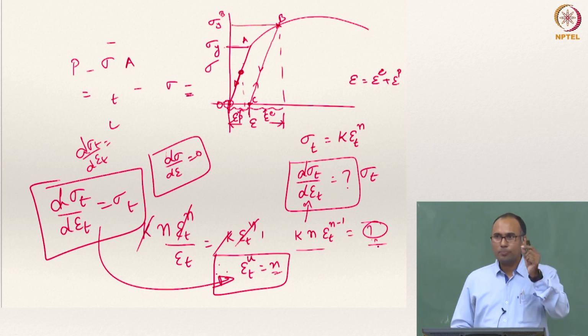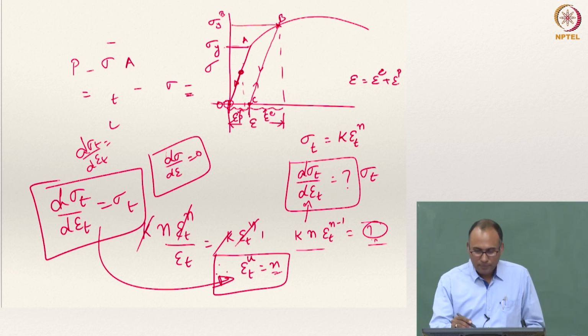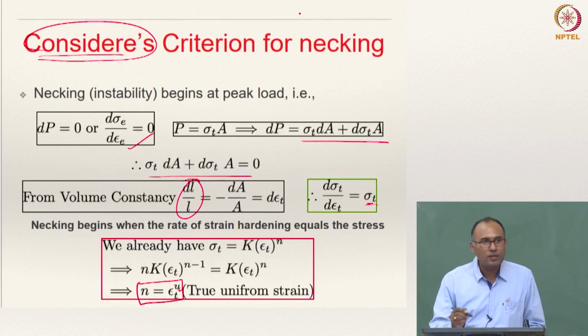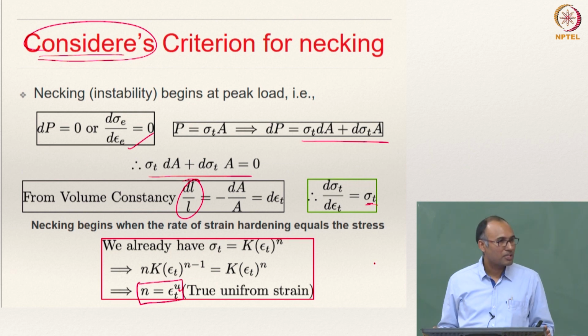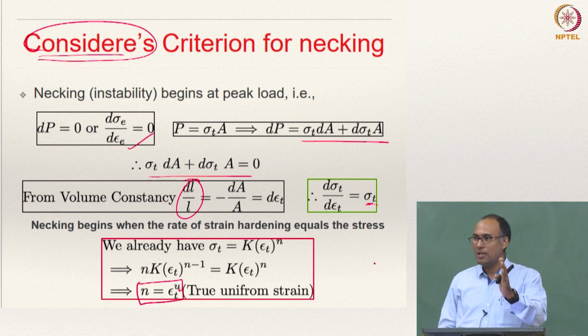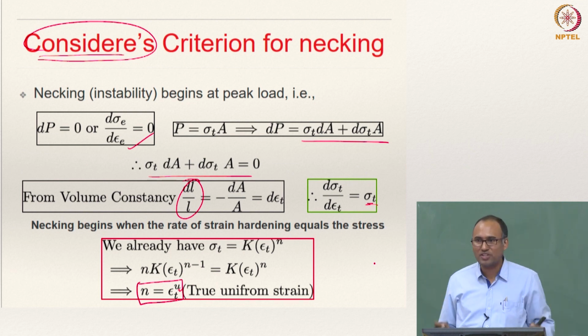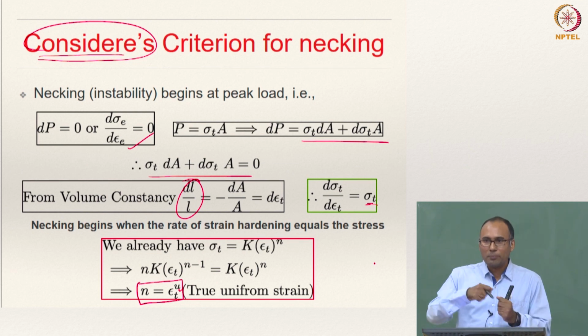So the most important point to realize is that when we are moving along each and every point on that line, you are actually transforming your material. It is not the same material anymore. It may have the same elastic modulus, but it definitely does not have the same yield strength. Its yield strength has changed. You have actually changed the material for good by doing plastic deformation.